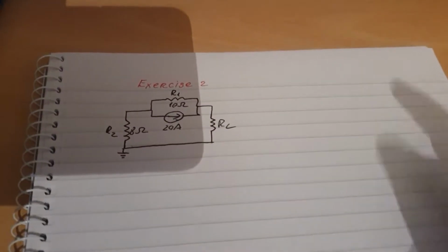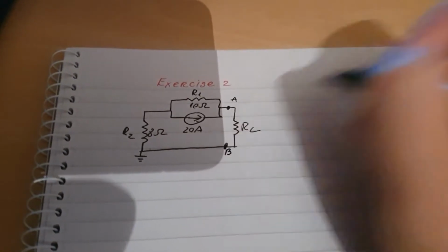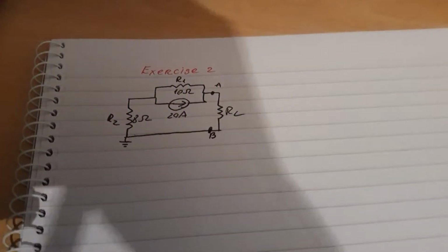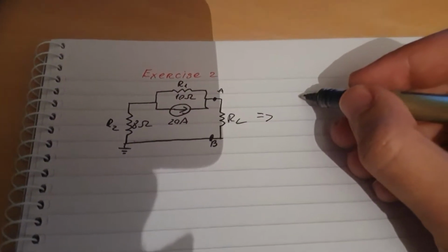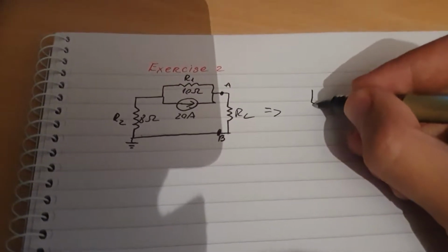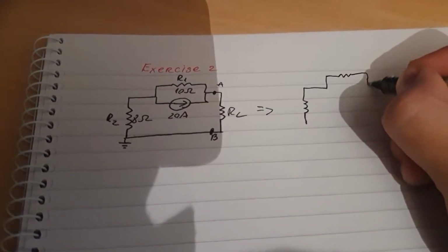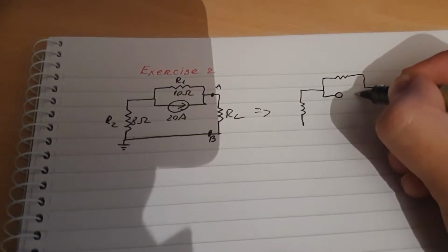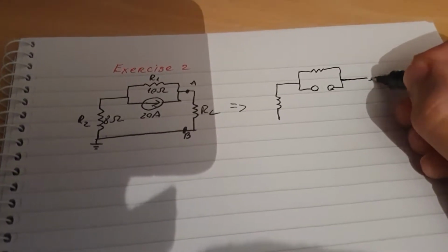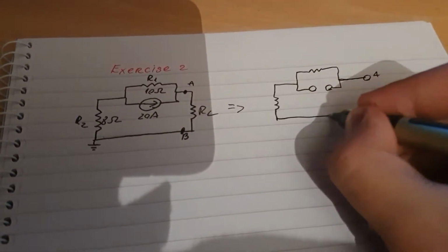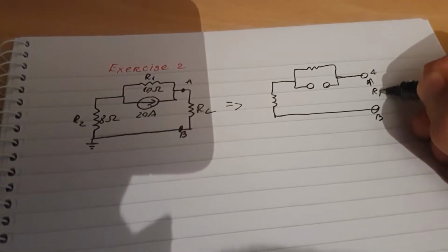First off, the first step is to decide which resistor we're going to find out, which will be that component right there. And then the second step will be to change the diagram to find the total Norton resistance. So there's one resistor here, there's another one here. Very importantly, this one will be an open, there you go, because it's a current source, and current sources are opened. And there will be A, and then there will be B here, and this is supposed to be for RN.